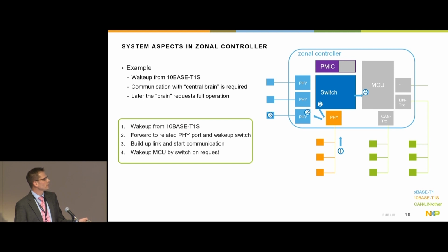But it is also forwarding the wake-up to the PHY. On this side, I said, okay, it's just configured to have one port which should be woken up, so communication can be established, and then it might be that later on, depending on what was negotiated in communication, the ECU is also needed. Then from the switch side, you have the possibility to also wake up this device. But this is fully flexible because you do not need to have the microcontroller running if it is not needed.